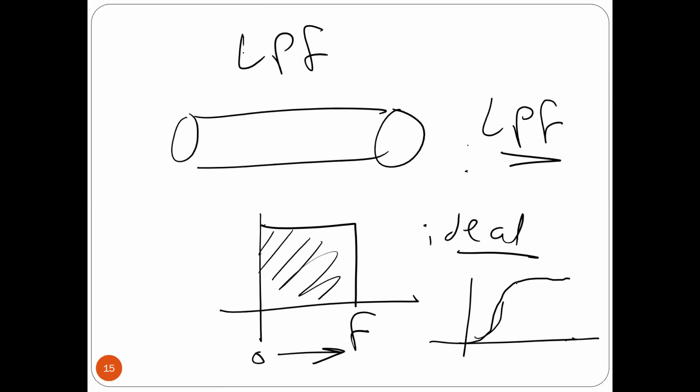Yeah, reality has something like that, and then goes this way. Because this is a certain frequency, it cannot pass. So most low pass filters have some difficulty passing or accepting the DC component, the low frequency. You got what I'm saying? Because the channel is not going to allow the transmission of low frequencies, it's the same thing for the receiver. A good encoder should not have a DC component.